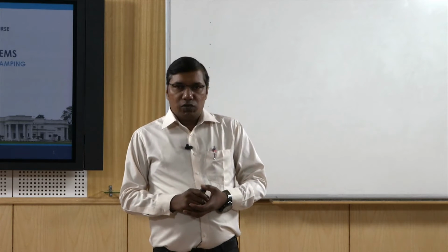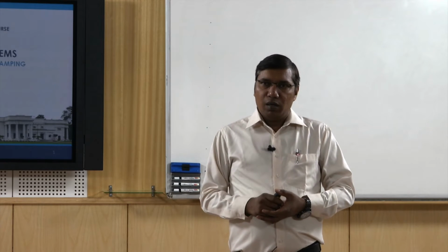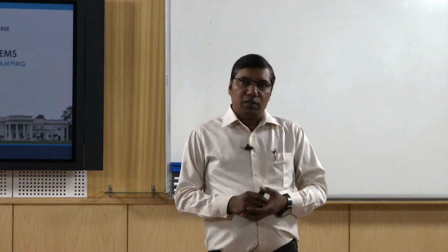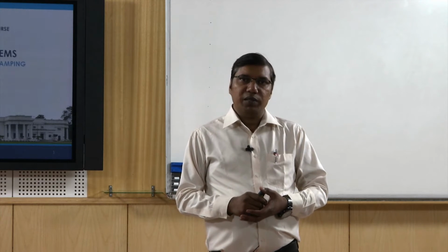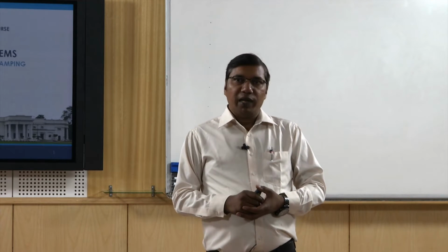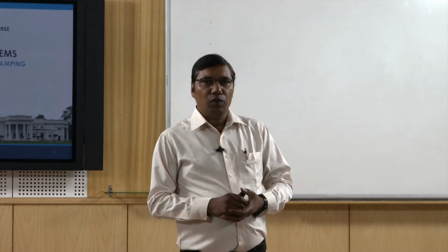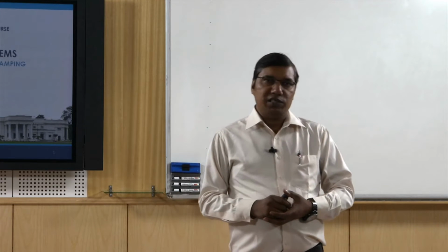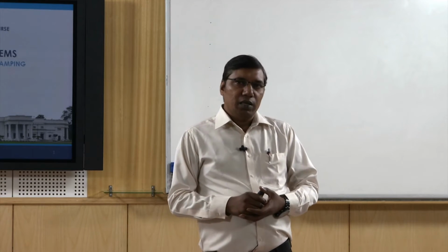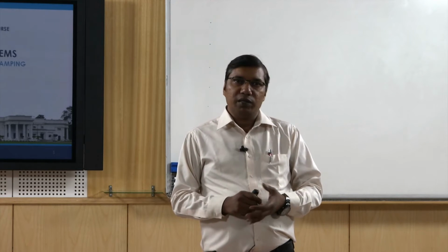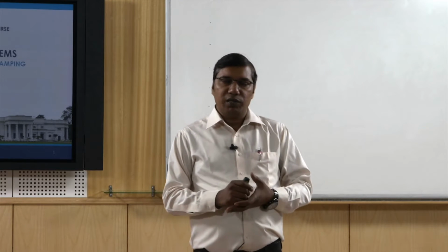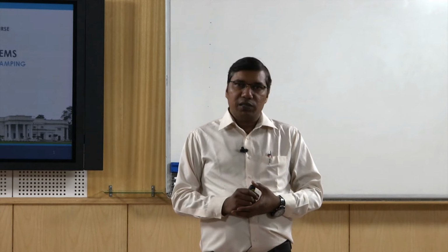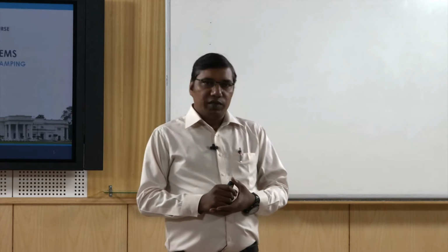Okay. So there are some easier ways to study this kind of system. One is that we convert this kind of damping, like Coulomb damping, to an equivalent viscous damping. How and why can it be convertible? So first, why? Because the basic function of damping is energy dissipation. In a viscous damping case, there is damping in the slow movement of a piston in a fluid. This kind of damping is regarded as viscous, and there is energy dissipation. But in friction also there is energy dissipation.